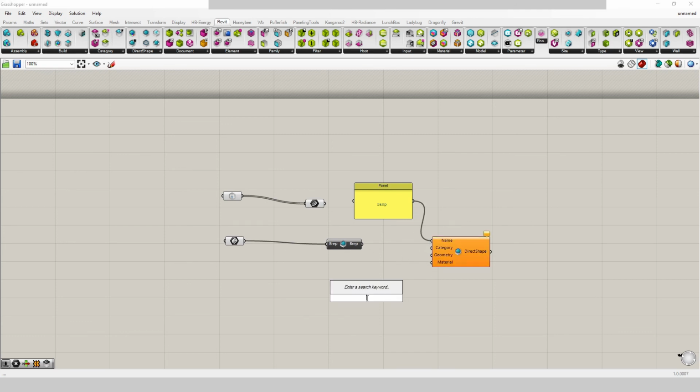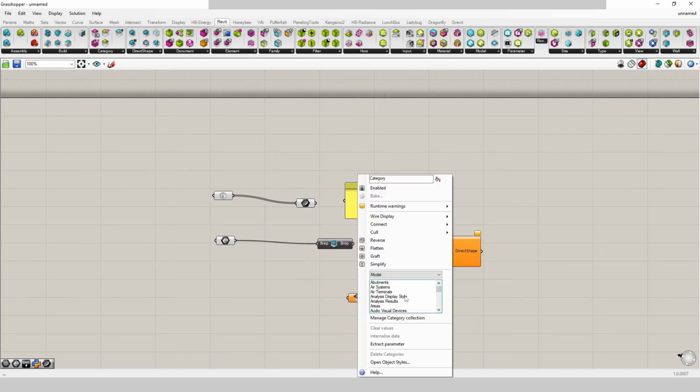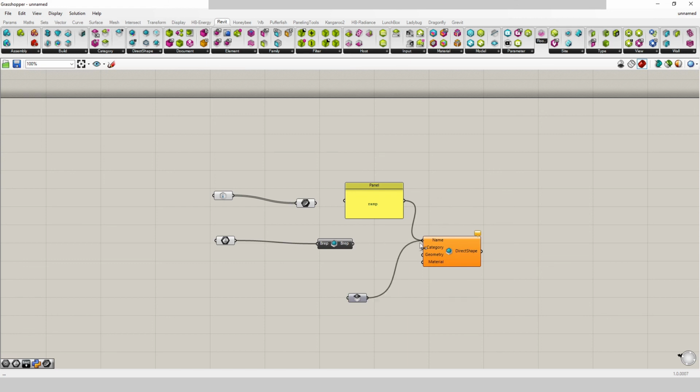Category, you could double click and say category. Then you hit enter, and then you right click on category. You can pick a different category, right? So you can say I want this to graphically show up as a generic item. And then in Revit, you can set all your, when you cut through something, you could say make all my generic items or all my floors, like what I just picked, post shade black. So in section, this Rhino.Inside geometry will still show up graphically how you intend.